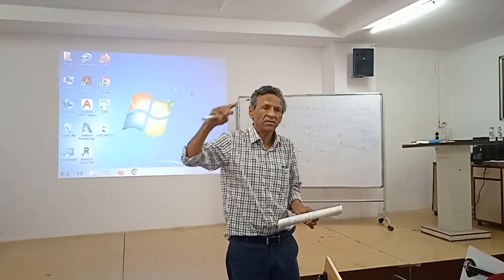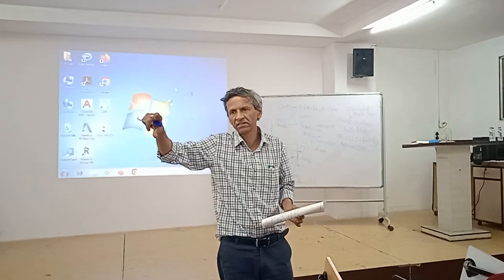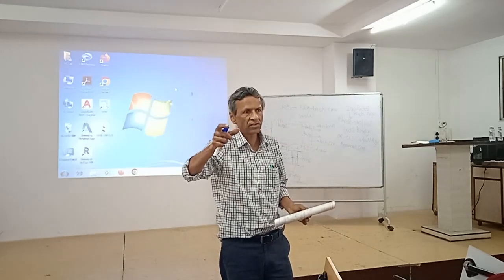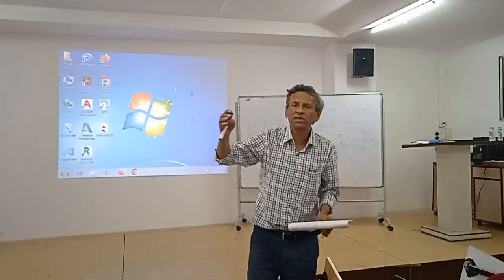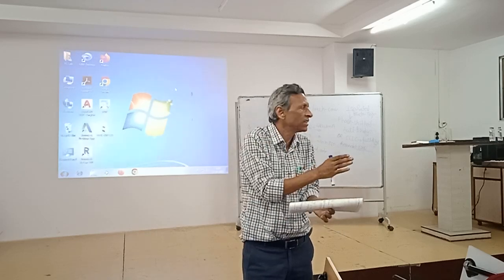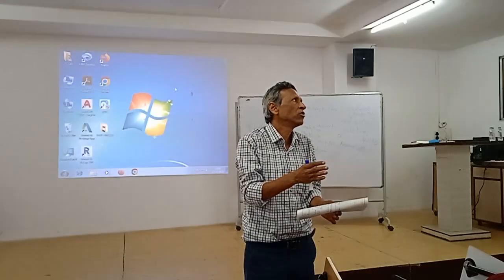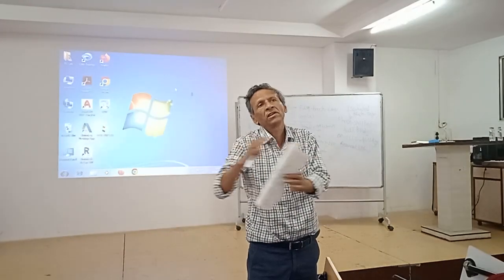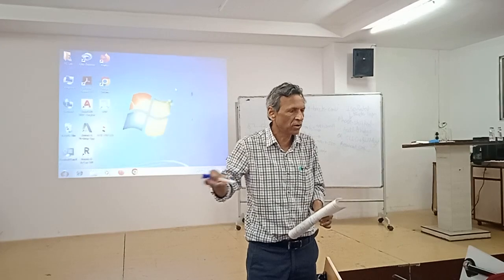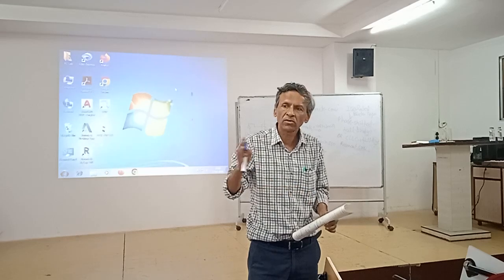Okay, so then you have to calculate, because based on this inductance and capacitance, and based on the switching frequency, suppose your resonant frequency comes at say 18 kilohertz, then you can vary that in the sub-resonant range, because in the sub-resonant range it works predominantly as an inductor, beyond the resonant range it works as an inductive circuit, and below it works as a capacitive circuit. Okay, so you have to vary that.